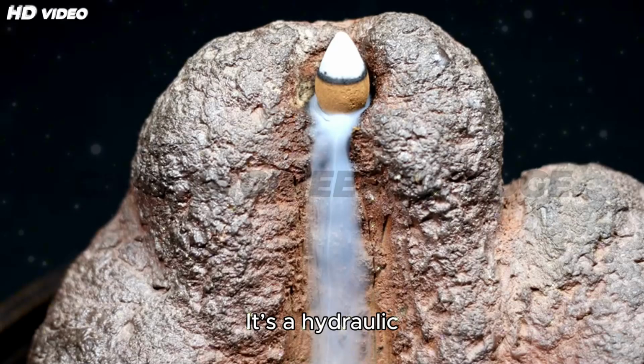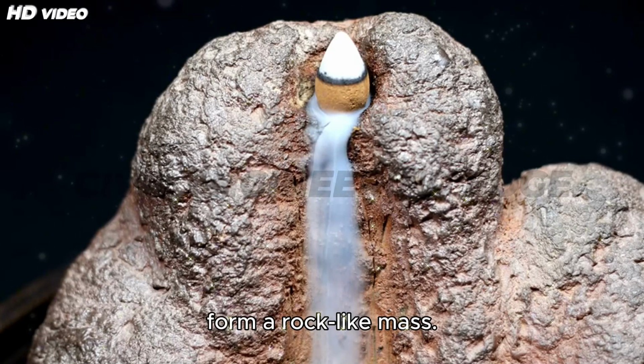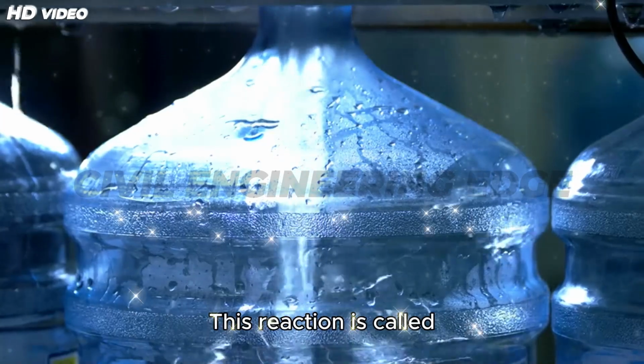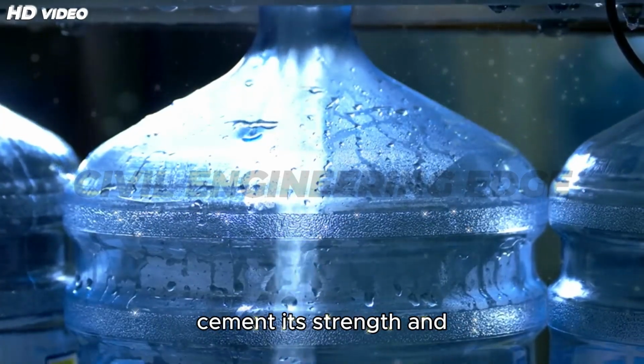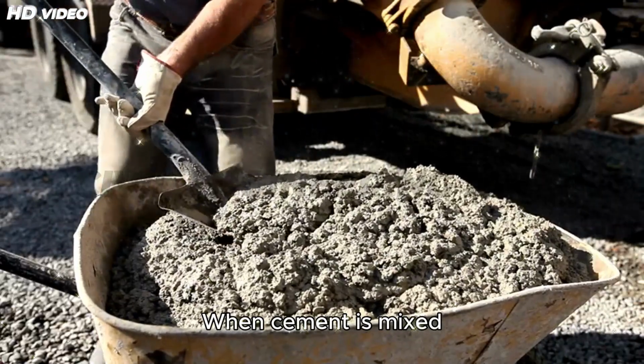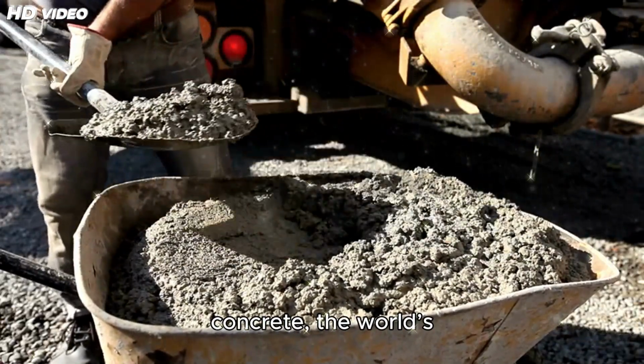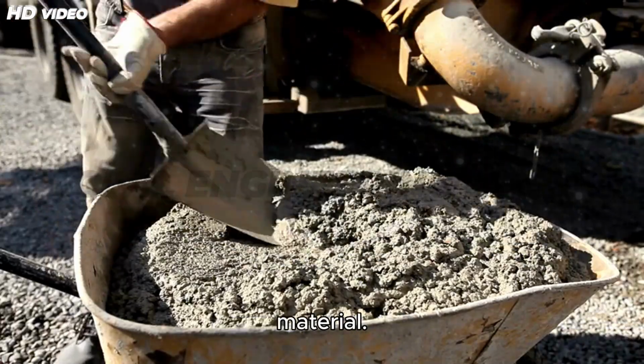It's a hydraulic binder, meaning it reacts chemically with water to form a rock-like mass. This reaction is called hydration, and it gives cement its strength and durability. When cement is mixed with sand, gravel, and water, it forms concrete, the world's most used building material.